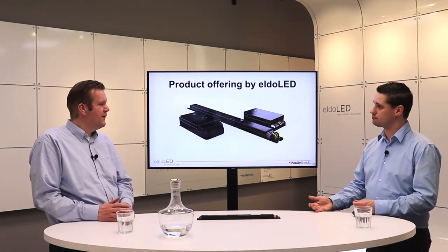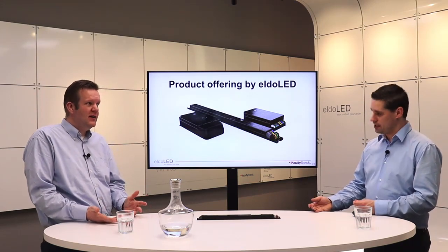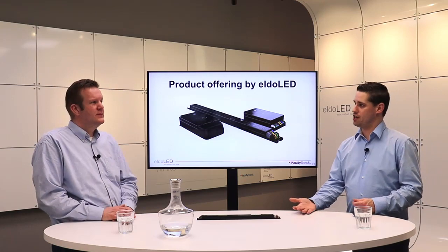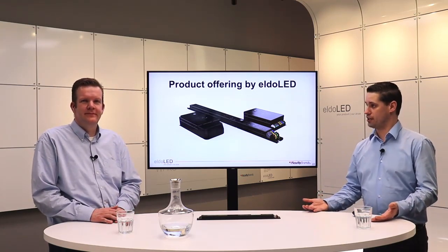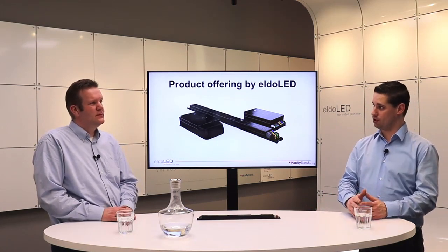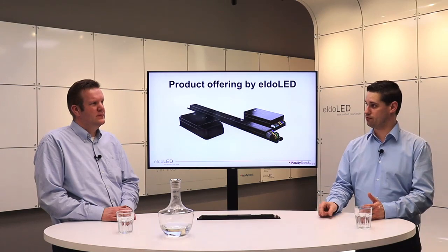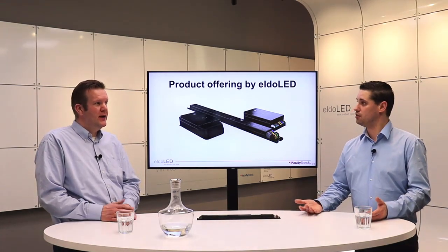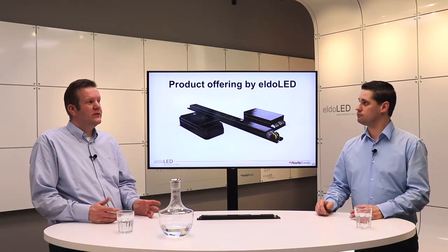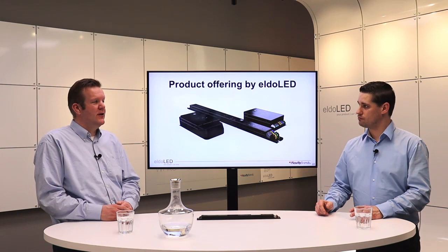Okay, and I see it's a 4-channel device. Can it also be used as a 3-channel, 2-channel, or 1-channel? Yeah, we can configure the device in such a way that you can enable or disable certain channels. So if you want to use a 4-channel product to act as an RGB product, you can simply disable that 4th output and use it as a 3-channel device. So make a different profile in FluxTool or order a different CI code with our sales department, and you get the correct driver as needed.